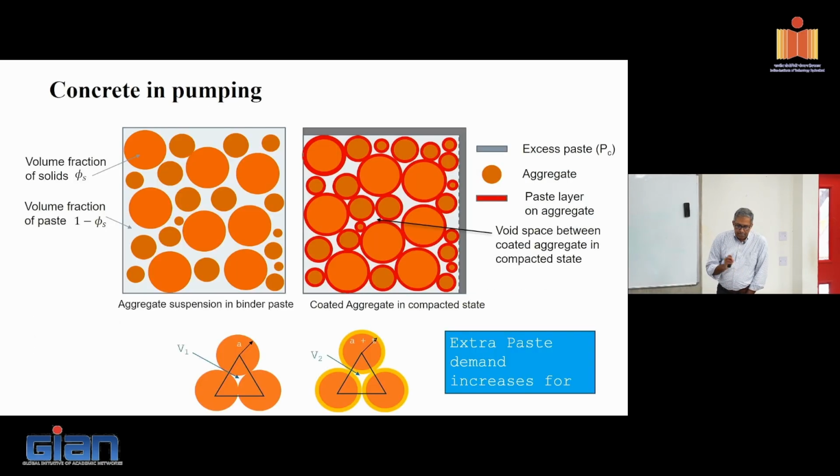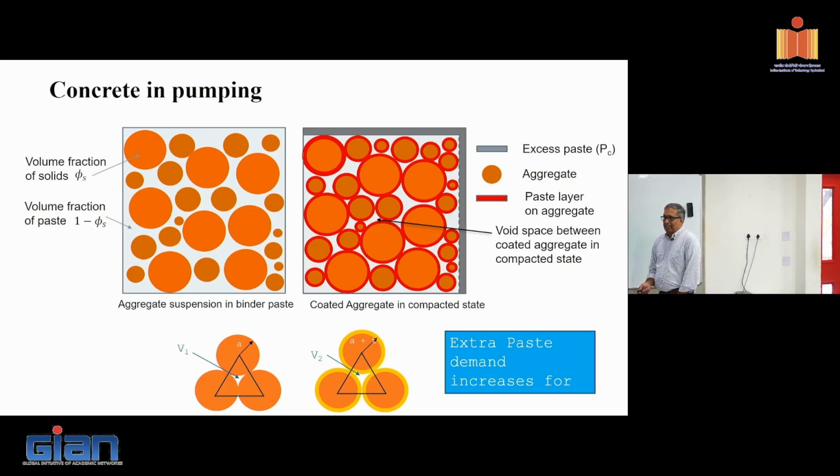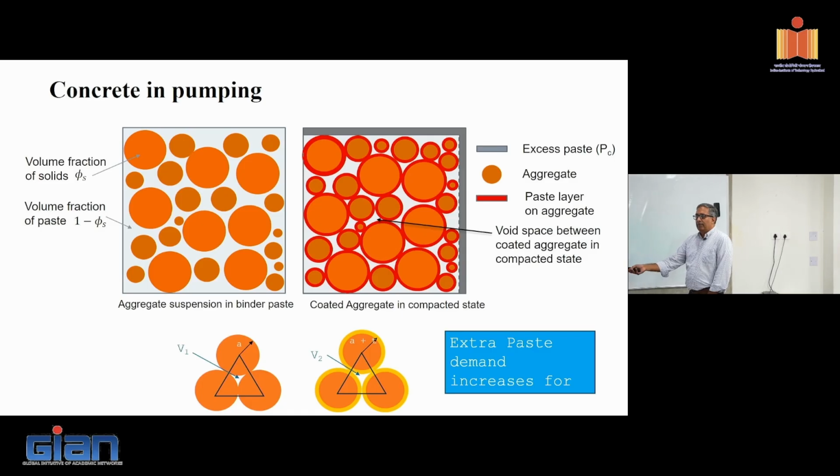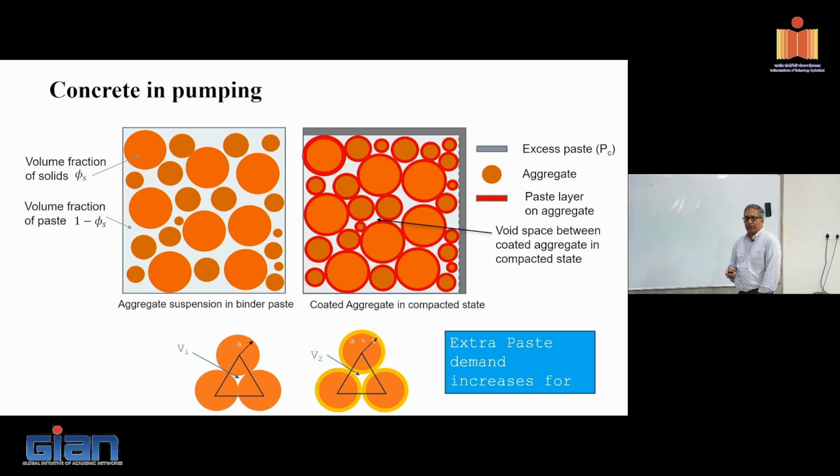Basically, this is the fundamentals of concrete mix design. We play with our aggregate content, packing, paste content, composition of the paste, and how much water to cement ratio. When all else is done, bring in some admixture to control the final outcome. Right? And fundamentally, it is the rheology of the paste that determines the rheology of the concrete.